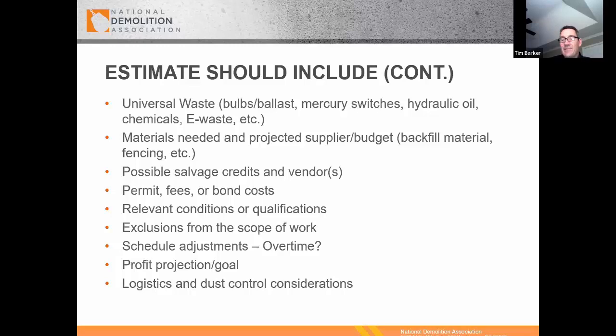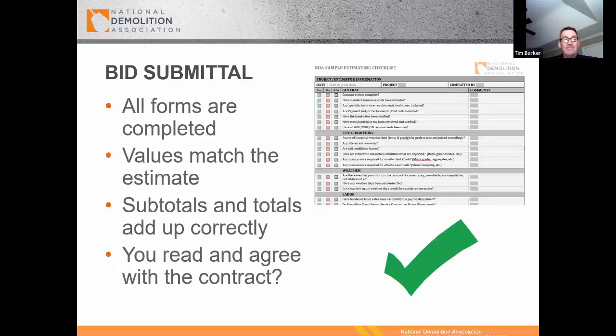The permit fees, sometimes the permits have some fine print that will determine or direct you to do certain things or not other things that you should be very aware of. Exclusions from the scope, overtime, other things that need to be considered as you develop your estimate. When you develop that bid, hopefully you have some type of check sheet that allows you to understand that you've captured everything and that somebody else maybe has reviewed your estimate.